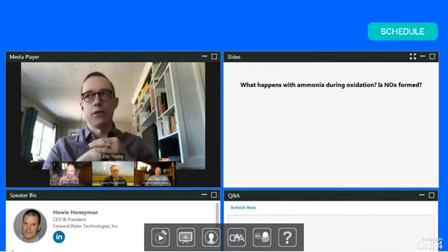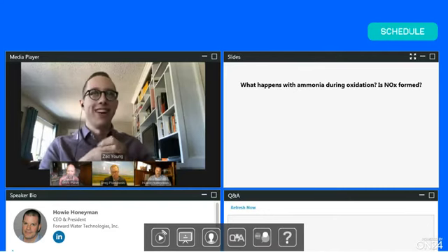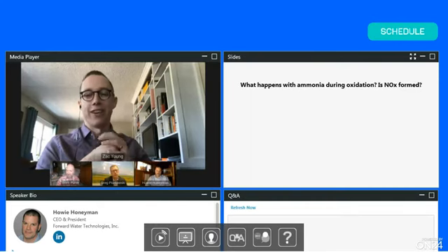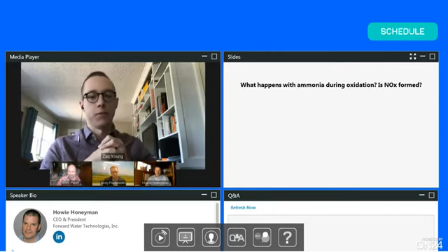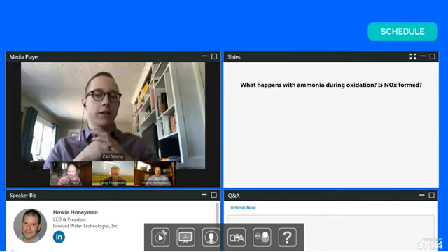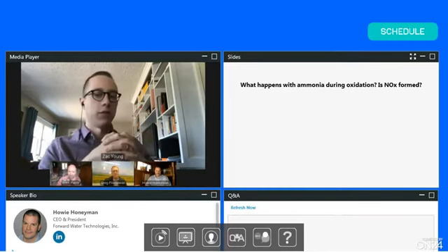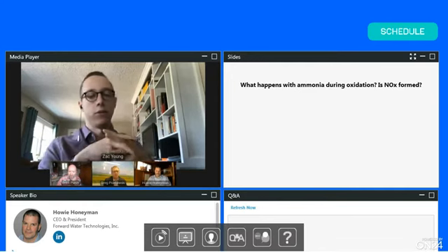There's a pretty deep number of pathways that the oxidation process goes through, and I won't pretend to have exact know-how of what will be in every water matrix off the top of my head, but yes, it can be oxidized. What I will comment on is that for most of those compounds we're oxidizing, they would be fully degraded if treated to the fullest extent. So in terms of concerns about reaction intermediates, the process isn't limited to a certain degree of oxidation, so it should be able to proceed right through.